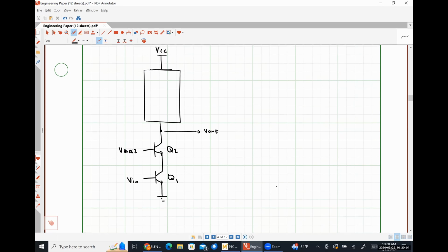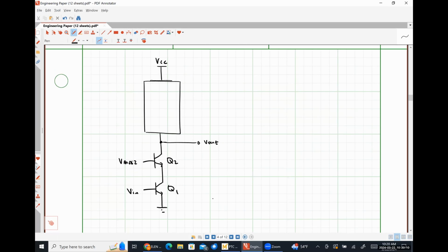our output voltage. So my question to you guys is, what do we want to put in that box? And I'm not asking for anything super specific here, but what considerations should we take into account, right? And so let's contextualize that by thinking about our voltage gain in particular, okay? So for our cascode amplifier, we know that our voltage gain is negative gm times a resistance R out.